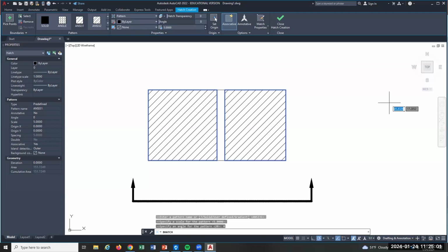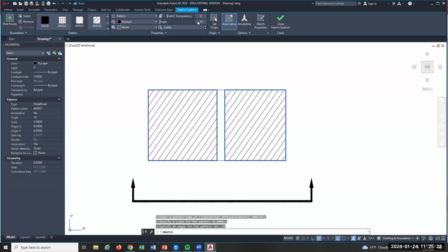So hatching should be at an angle, and it should not be close to any geometry of the part. In other words, it should be like this. None of those hatch lines line up with the part, right? If this part had a 45 on this corner, then I'd want to change this angle to something different. Make it steeper. Just get it different than the part lines.